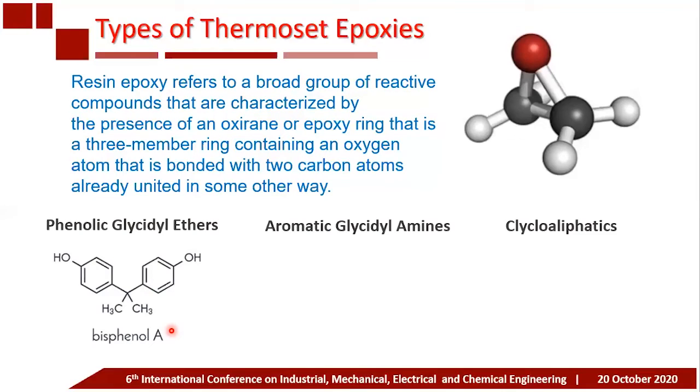The structure of the phenol-containing molecule, the number of phenol rings, distinguishes different types of epoxy resins. And then some modification of the ratio of epichlorohydrin and bisphenol A during production can generate high molecular weight resin. This type of resin increases viscosity, and hence these resins are solid at room temperature.